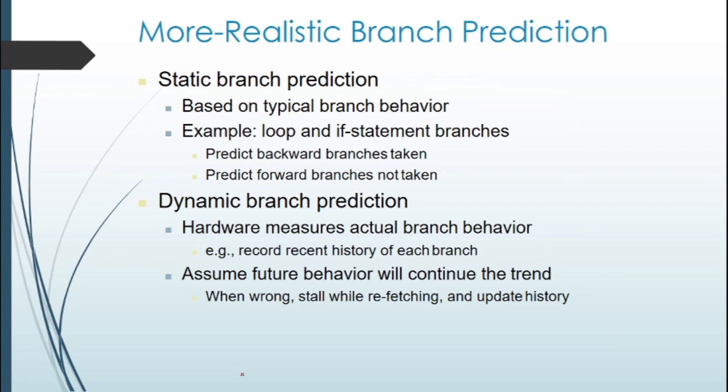A few little things before we complete this whole topic. There are more realistic branch predictions rather than just the not taken branch prediction that we just studied. There is static branch prediction, where we base the prediction on typical branch behavior.